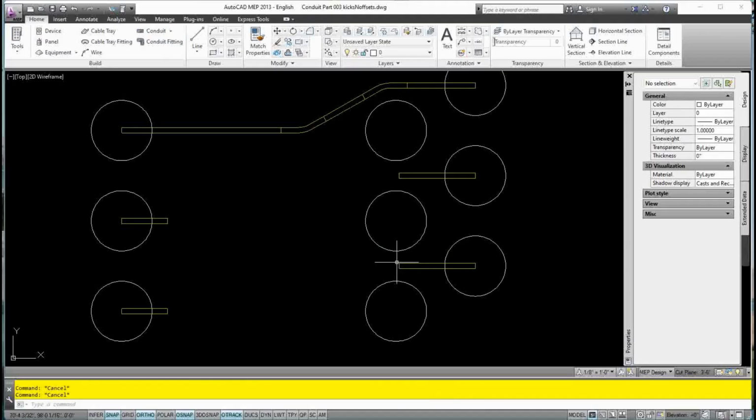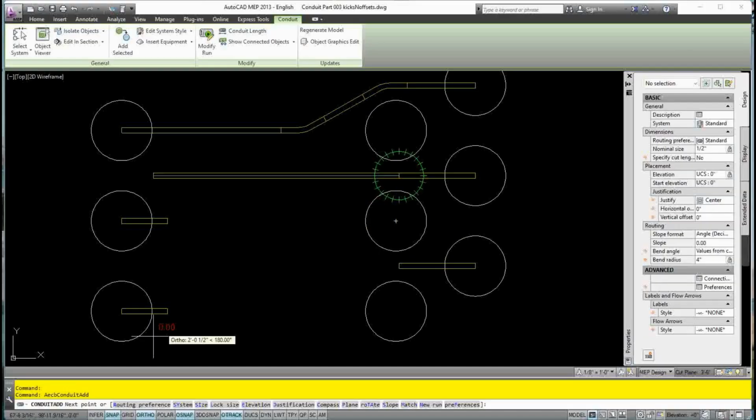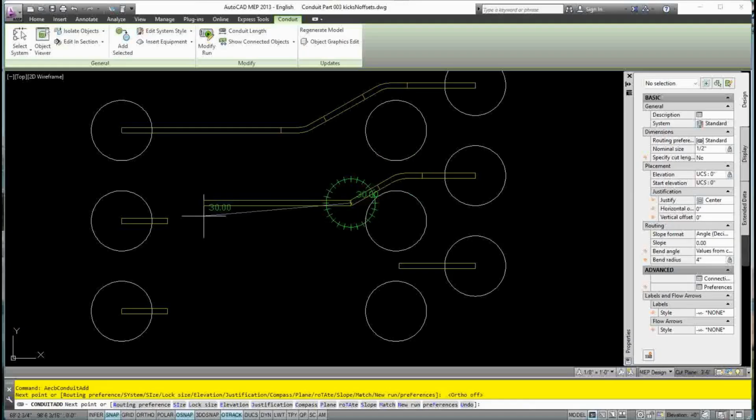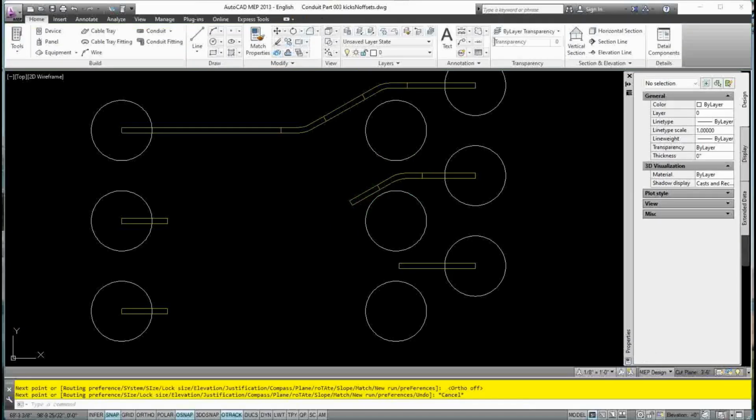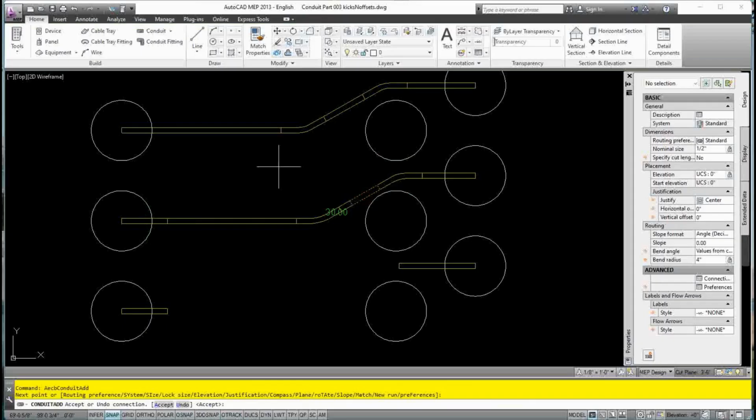All right, so let's say you want to experiment with different angles just to see how they look in AutoCAD. So with this scenario here, you're going to click this, and you're going to click that, and of course, we're stuck, right? So let's undo the ortho. So now we turn the ortho off, and we can pick an angle. Doesn't look like 45 is going to work very well. So let's go with 30. All right, we go with 30. And let's escape. And let's come from this direction. Do you think 30 would connect with that? Let's see. It will.